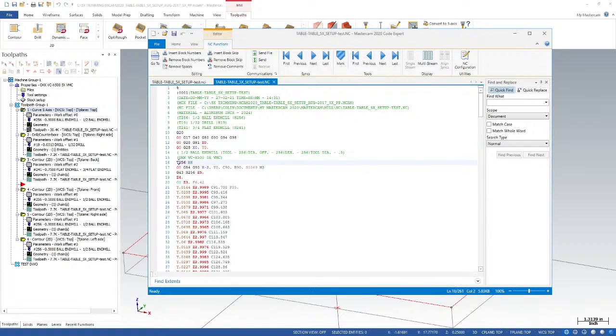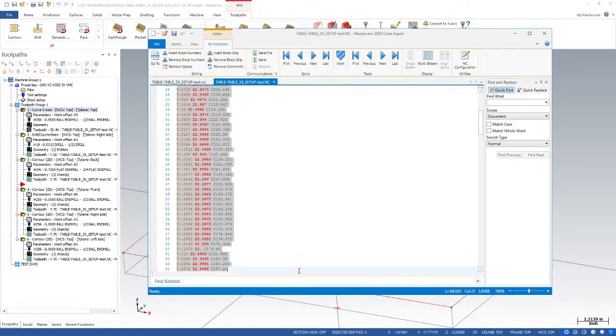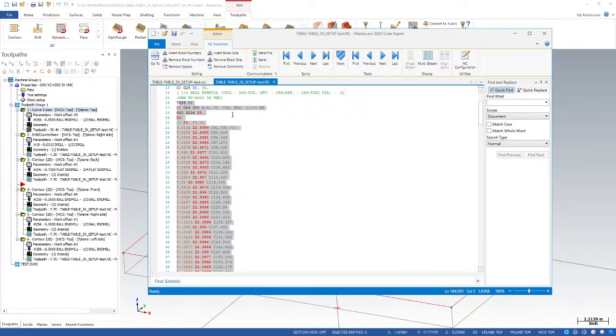This first operation, you'll notice, is a 5-axis operation. So we're starting at C90, B90, and we're positioning in XYZ. So we're positioning in XY here. We've rotated C and B. We're coming down in Z and turning on tool length compensation. We start out at Z5, then we go to Z4, then we feed down to Z3, and then we start rotating.